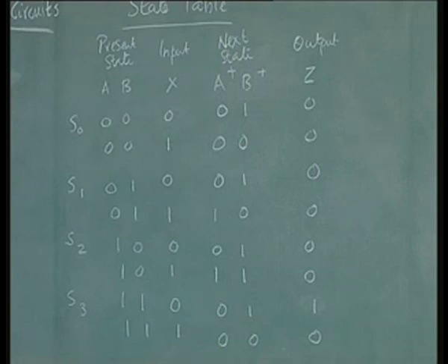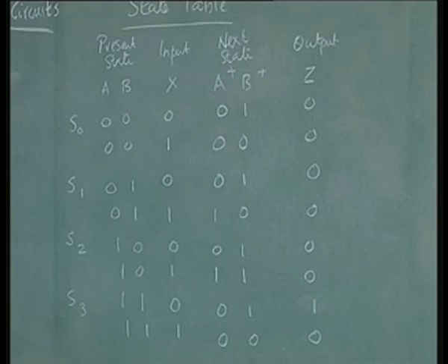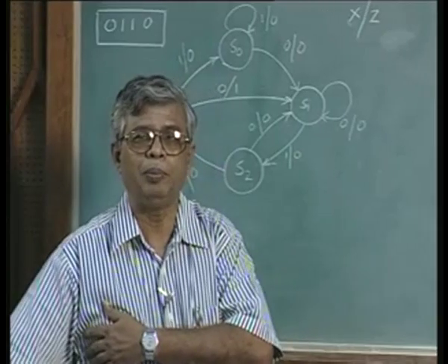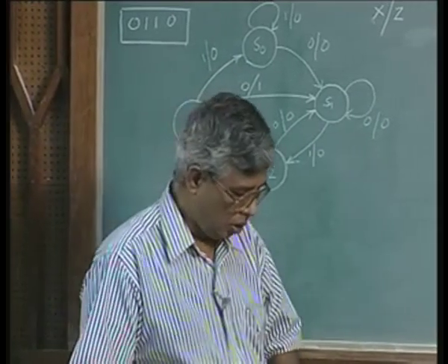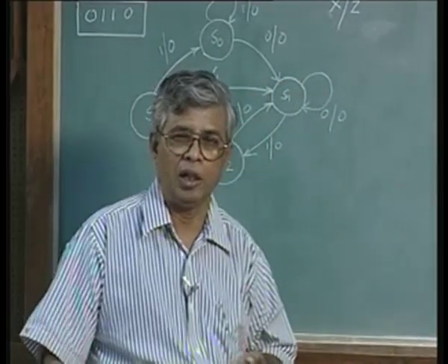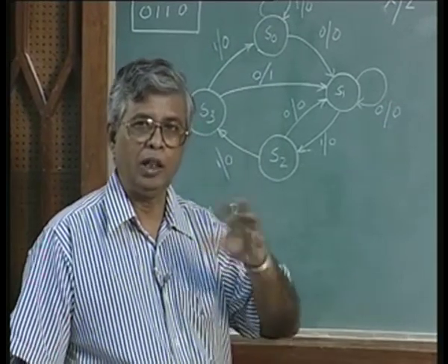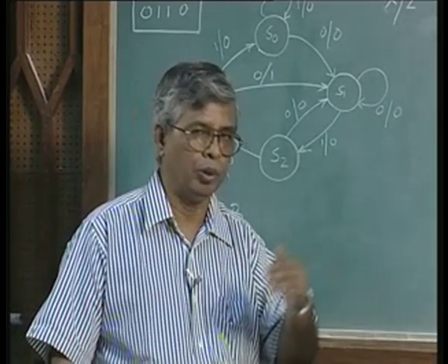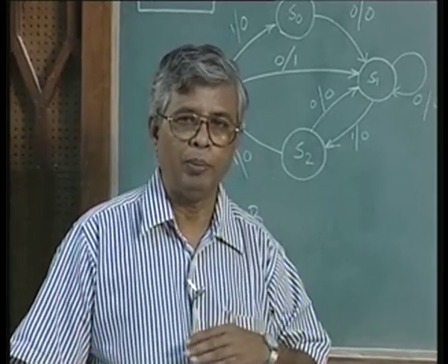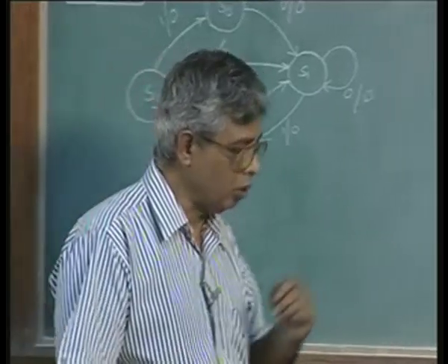And now instead of going through the reduction using Karnaugh maps as we did in the last lecture, using gate implementation, I am going to straight away say that I am going to use multiplexers as combinational building blocks. Since we already saw the implementation of combinational logic using multiplexers, we should be able to easily fit in. We know that any combinational logic with the definition of the input output relationship can be implemented using an appropriate number of multiplexers. So, let us try to do it here.